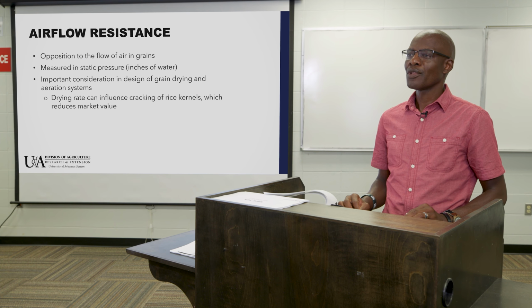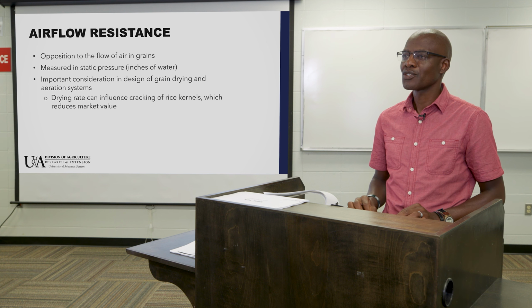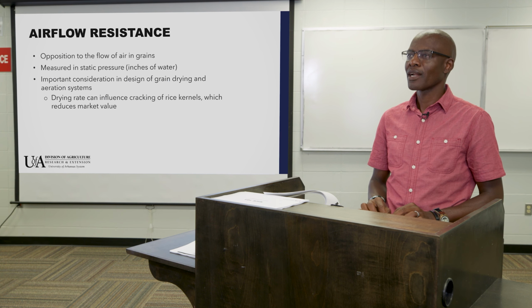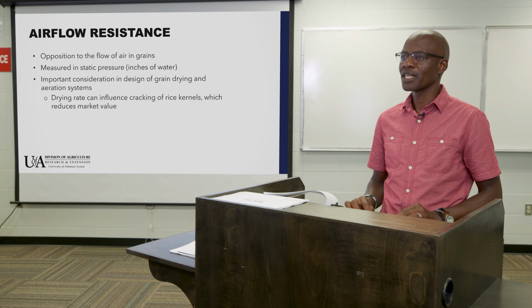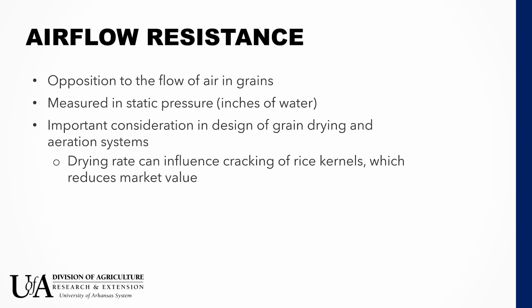So what is airflow resistance? In simple terms, this is the opposition to the flow of air in the grains. As you would expect, if you have rice in a bin and you're trying to push air through, it would move completely different from the case where you don't have rice inside that bin. And typically we measure this airflow resistance in static pressures, expressed in inches of water. It's a very important consideration, especially in the design of grain drying and aeration systems.